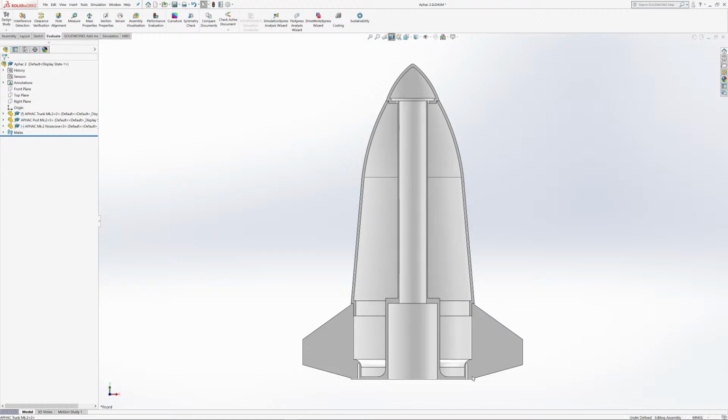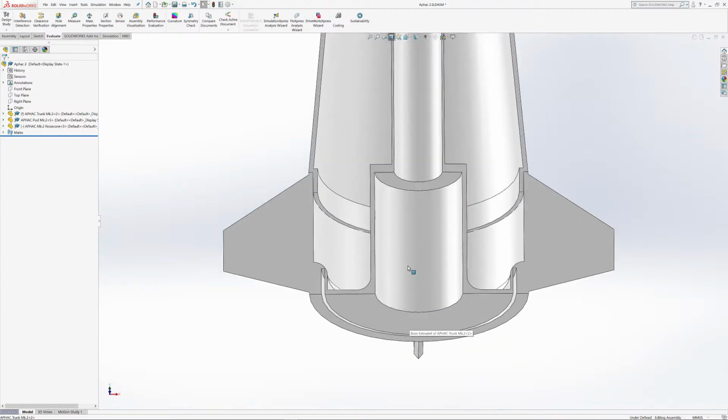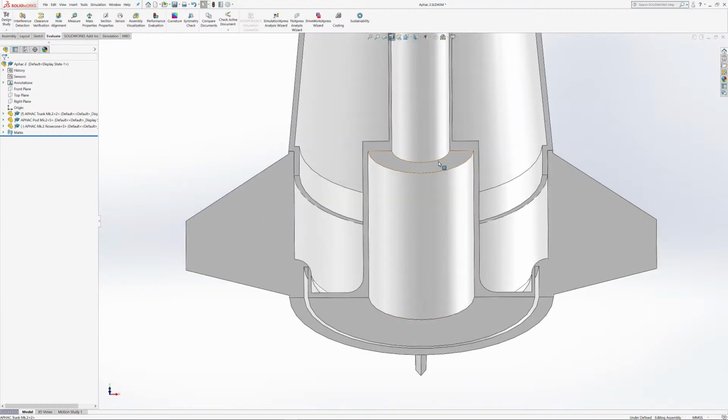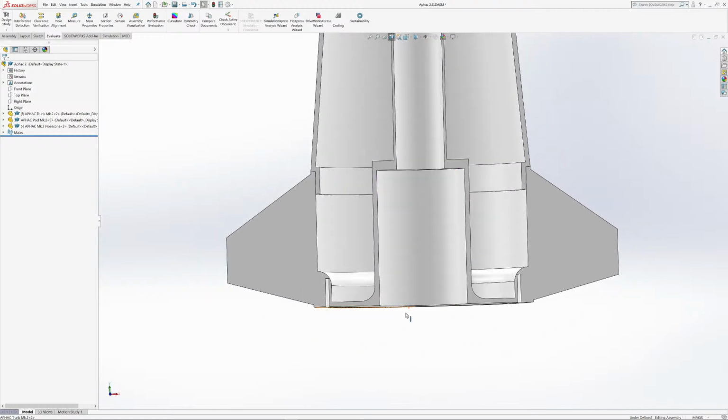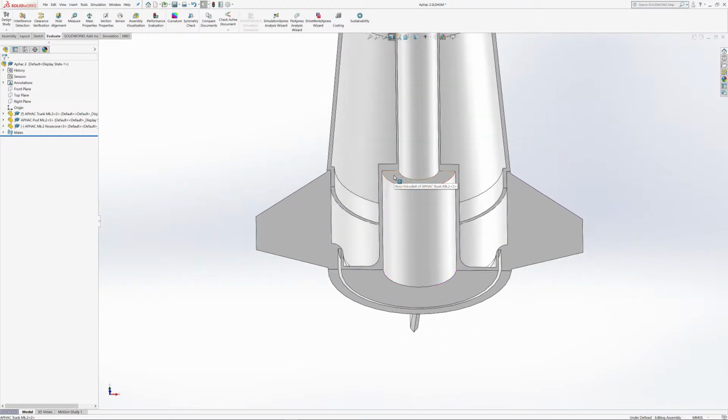Because when you're printing something, or when you're building a building, you build from the ground up, and it's like an arch. If you don't have the keystone of an arch, it's not going to be structurally sound. So you usually have to have something to hold up that arch until you have the keystone, or until it's done, and then you can move that arch out of the way. Well, in 3D printing, that's called support material. And so for this design, you would have support material that would build up here and in here up to here, and support that while it's printing.